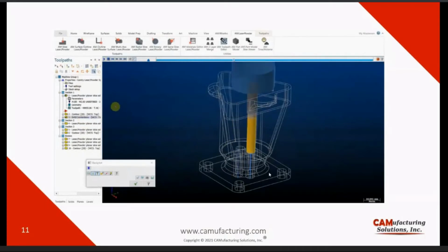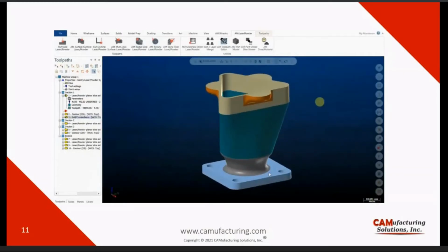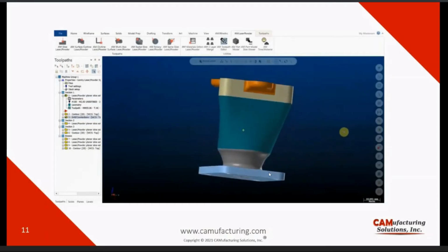This would be a lot easier than if we were to have the entire part from a single billet and using regular machining, and have to use a long drill that would actually have to go through the whole height of this part. So it's a lot easier to do one step of additive followed by a step of machining for this specific case. And then followed by this step, we'll go ahead and print the rest of the cup using regular additive.